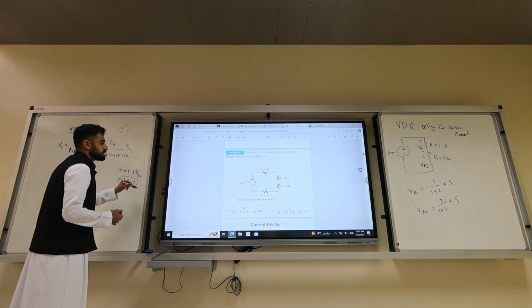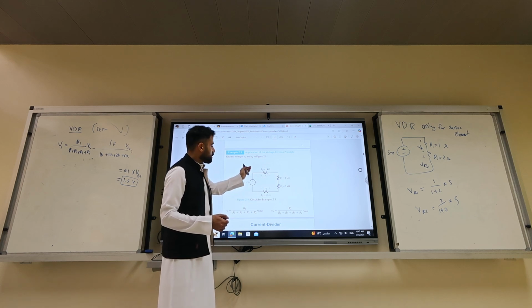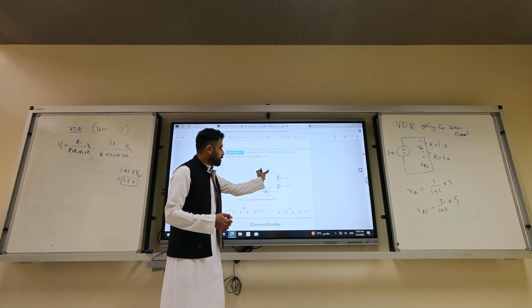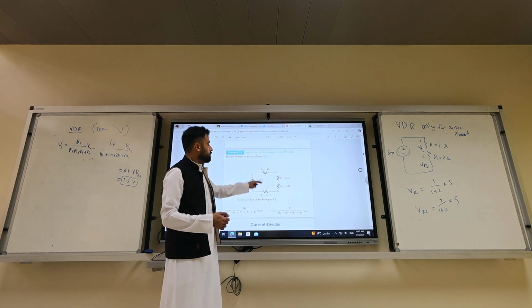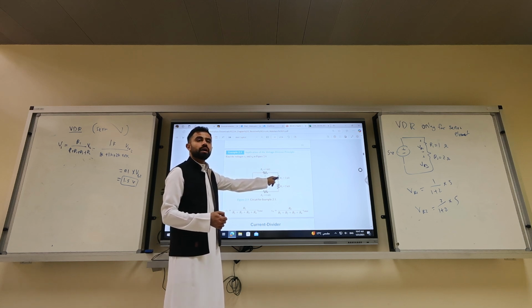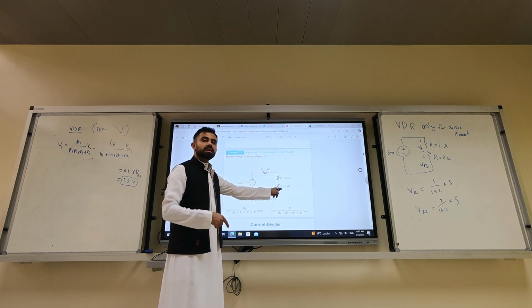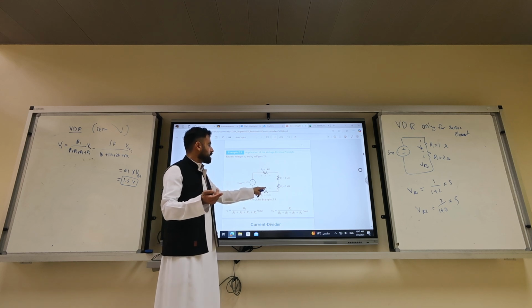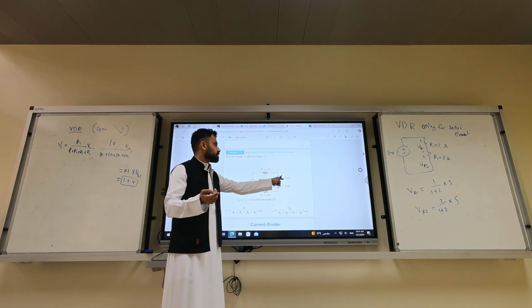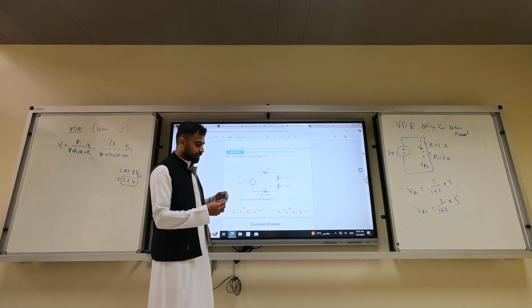You keep the same. At the end, if you sum by KVL, V total equals V1 plus V2 plus VR3 plus VR4. Also I can calculate VR2 by looking, same as VR1, because they have the same resistor. VR3 is going to be twice. Is it going to be twice? Do the math. VR4 is going to be equivalent to this voltage, because 1 plus 2 is 3. Is the voltage divider rule clear?